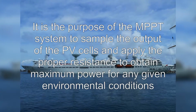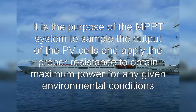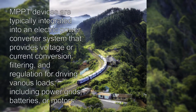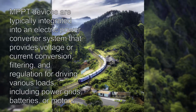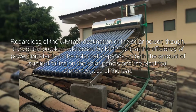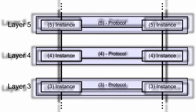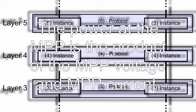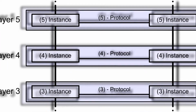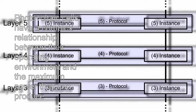the load characteristic there. Electrical circuits can be designed to present arbitrary loads to the photovoltaic cells and then convert the voltage, current, or frequency to suit other devices or systems, and MPPT solves the problem of choosing the best load to be presented to the cells in order to get the most usable power out. Solar cells have a complex relationship between temperature and total resistance that produces a nonlinear output efficiency which can be analyzed based on the IV curve. It is the purpose of the MPPT system to sample the output of the PV cells and apply the proper resistance to obtain maximum power for any given environmental conditions.